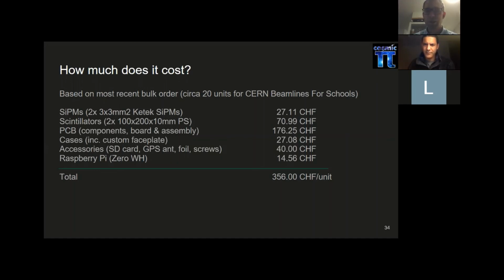Not having the microcontroller drive an external output as part of its detection loop minimizes your dead time and your variability in time and performance from cycle to cycle. But yes, there are other solutions. Our solution is a bit deluxe and expensive, but it's also simple and it works.